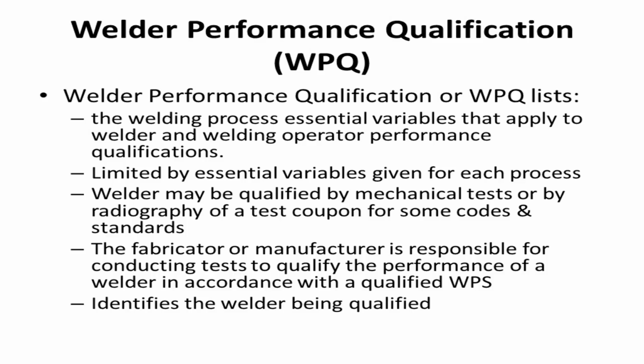So, welding performance qualification. This is the welding process essential variables. Let's see, I'm on the wrong page here. Okay. These are qualified by mechanical tests or maybe radiography, depending on the code. The fabricator, again, that employs the welder is responsible for their qualification here.